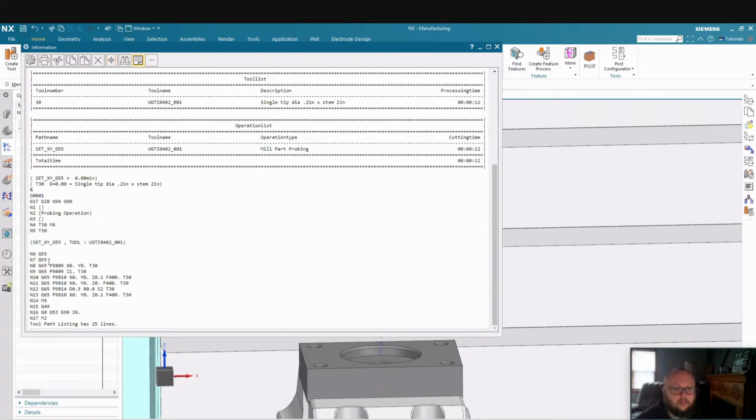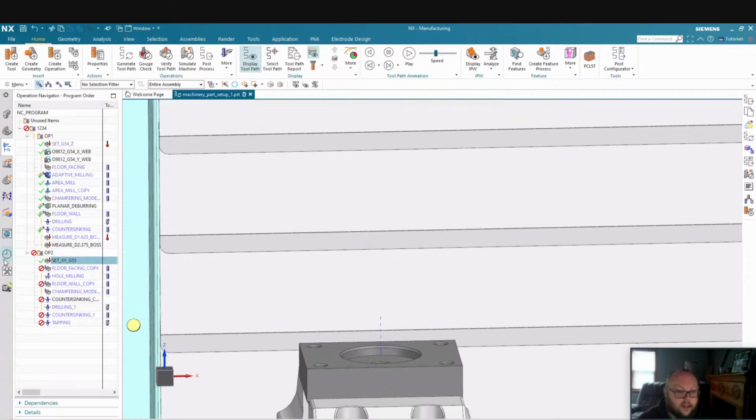And let's come down. Yep, we are calling offset G55. And when we do our probing, we're going to be using our 9814. We've already had a protected move position us at Z0, so we'll be down inside the part at that point in time. And we are writing to offset number 2, which is G55. So that's all looking good.